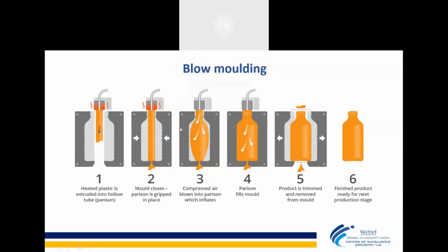Same case, blow molding. Blow molding is again a process where there is a two-part cavity where they use a small amount of raw material. It is subjected to high pressure and takes the shape of the mold inside. Blow molding is mostly used for bottle kind of things.